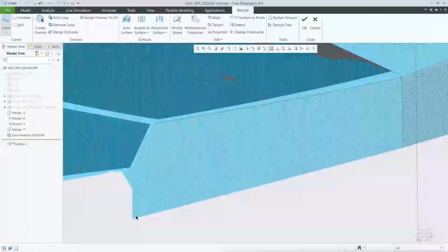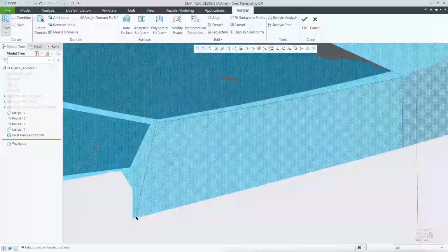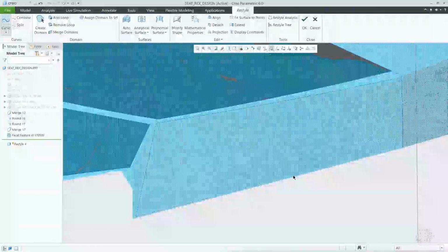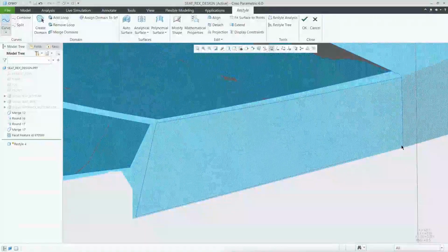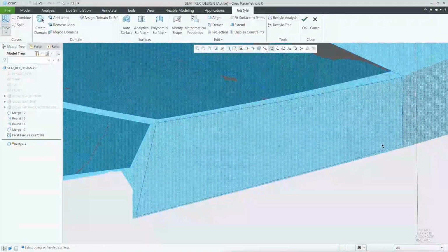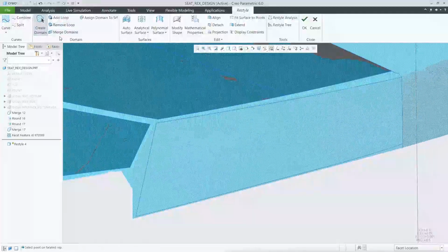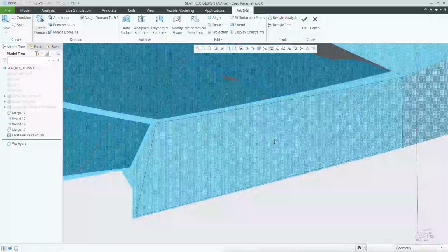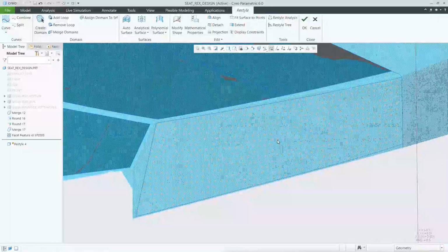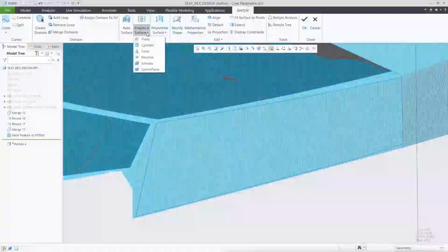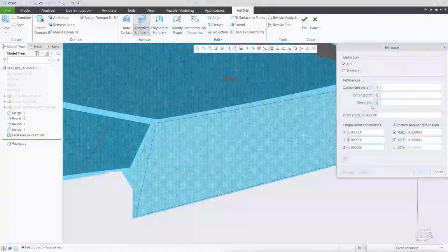If you want to follow tight right along those edges, you can change them up if you like to. There's nothing telling you you have to match up with the point cloud data unless you really do want to line up exactly with what you scanned in there. But from within here, what I want to do in this case is actually take the domain that's contained from within those curves. And instead of how I did it previously by building out the surface from those curves, we can instead build it out straight from a domain of points itself.